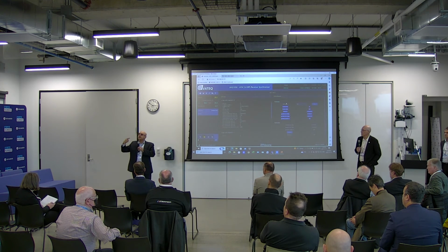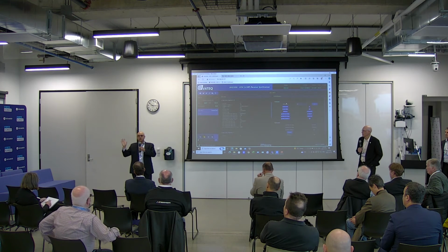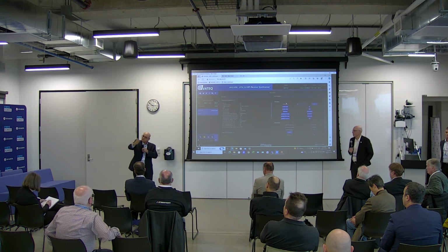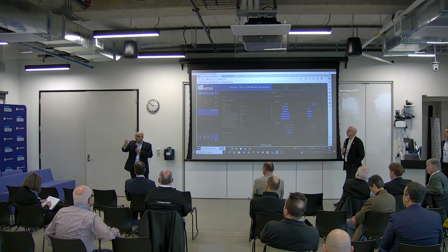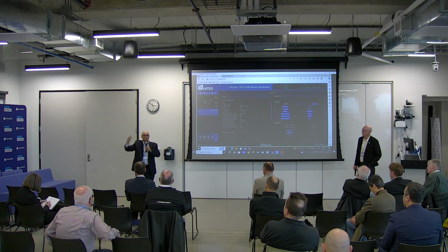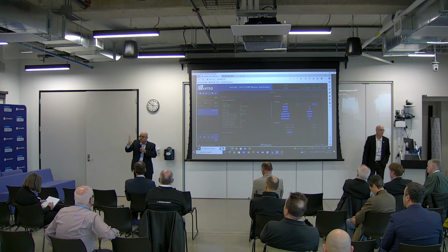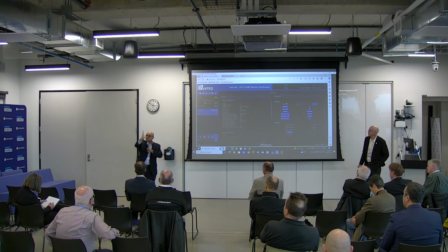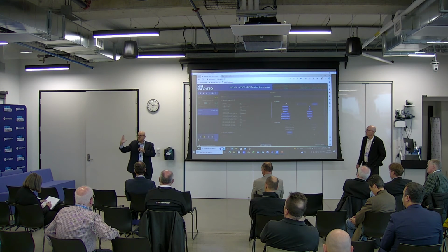But we are trying to tighten the budget at the transmission side, because we do not have control on the reception side, where there will be multipath. If it's a user who doesn't care that much, you can have an antenna over here, you can have some multipath, and you're off by, but you will not be jittering 200 nanoseconds. You'll be offset by about 200 nanoseconds or 100 nanoseconds or 50 nanoseconds. It will be jittering a few nanoseconds around that.